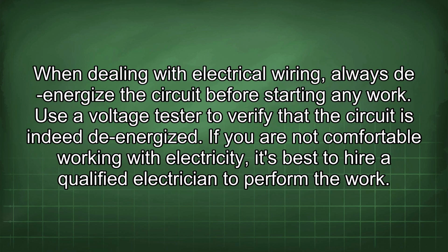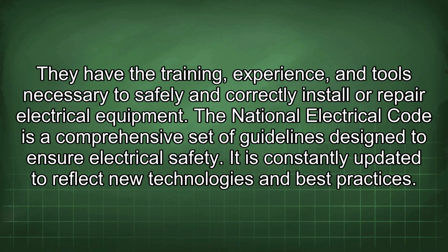When dealing with electrical wiring, always de-energize the circuit before starting any work. Use a voltage tester to verify that the circuit is indeed de-energized. If you are not comfortable working with electricity, it's best to hire a qualified electrician to perform the work. They have the training, experience, and tools necessary to safely and correctly install or repair electrical equipment.